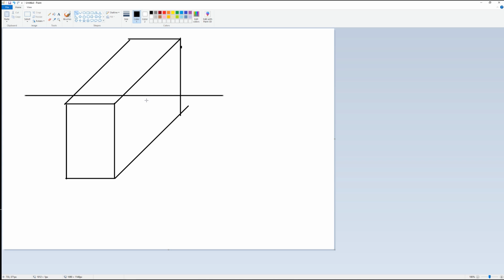any version of duct will work. And when we call that geometry intersect, Dynamo will look at geometry number 1 and geometry number 2, and it will only keep after that node just those pieces of the element which do intersect. So from our line, this will fall off, and also this. So the only piece of the line that will remain is the line going through the wall, and that is very good for us.